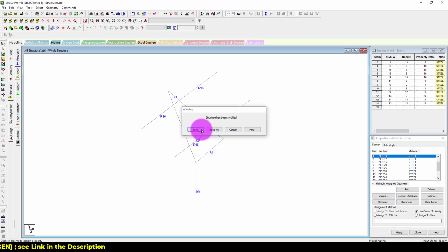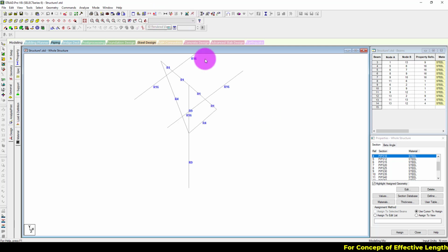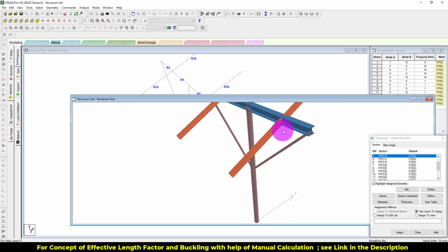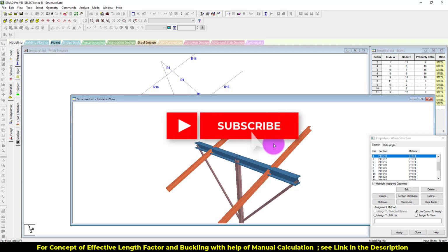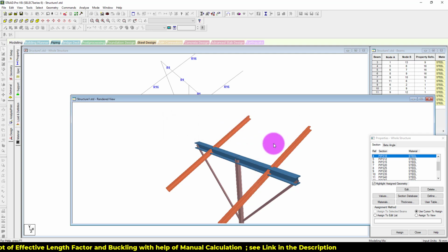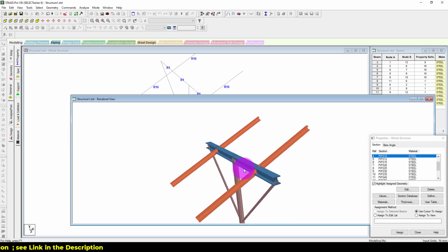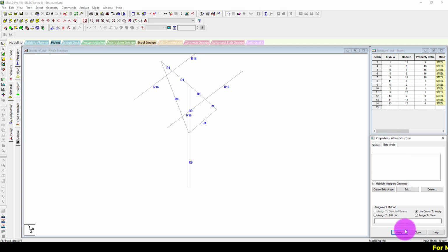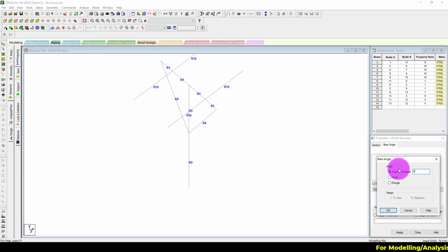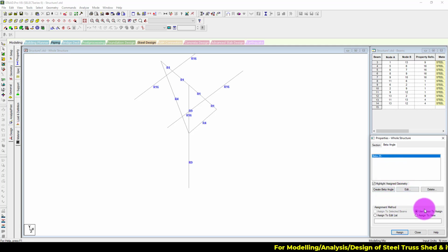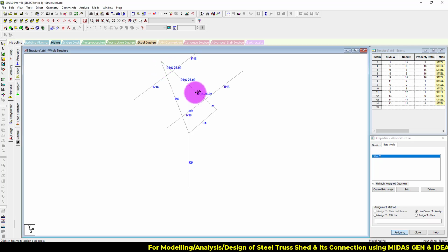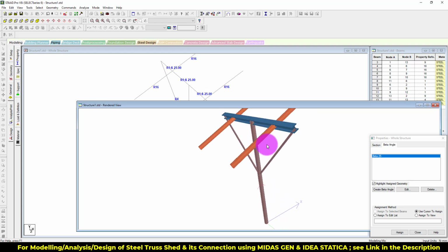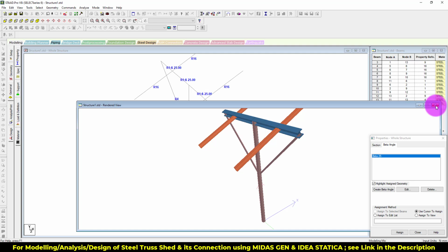for the bracings. Now when we click the 3D rendered view, this is our structure model, but here we can see that this particular beam, the blue beam, must be inclined with the same inclination as the tilt angle of our structure, of the solar panels actually. So to do so, using the beta angle, create beta angle, which is actually 25 degrees. Okay, and use cursor to assign the beta angle. Alright, now checking the rendered view.